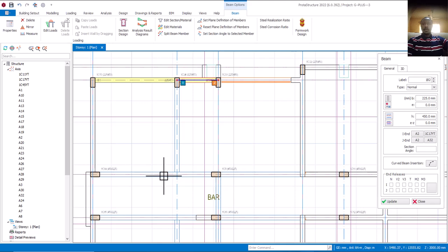Okay, so our slab thickness, we are using 150 slab thickness. Our cover is 25, which is okay. Then I'll come to load. On my load, we are talking of a hotel. First of all, my dead load is going to be 1.2, that's for tiles and the rest. Yes, we can use 1.2 or 1.5. Let's use 1.5. It's okay.